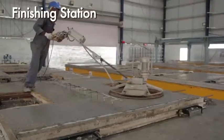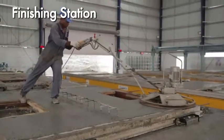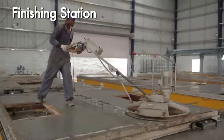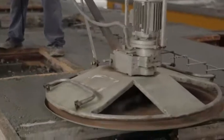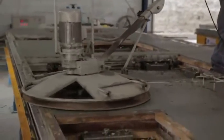Finishing station. Post the initial setting time of concrete, start finishing the concrete surface using power floats with disc blades. This step helps in removing the minor irregularities and makes the concrete dense. Use a segmented blade for power troweling to achieve the required finish.